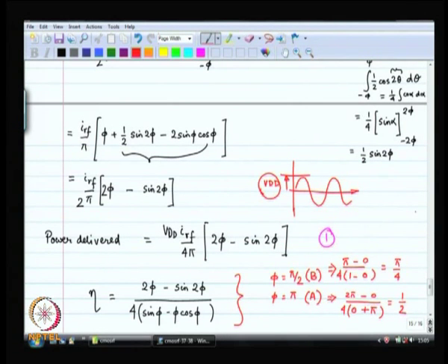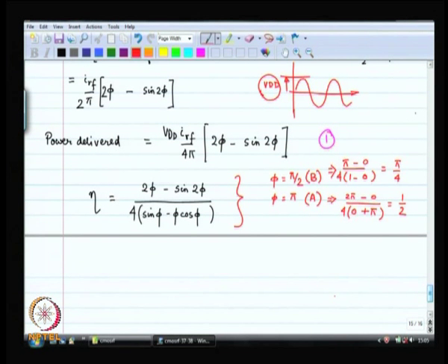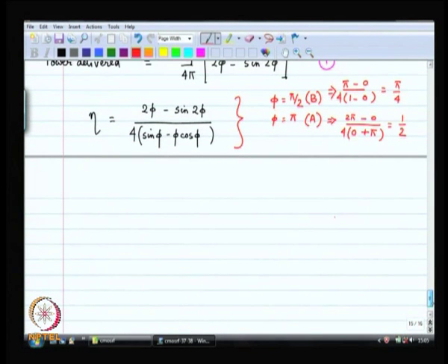All right, you need a little bit of room to allow for the transistor to remain in saturation. So, a little bit of room is needed over there. If you do not allow that room, then your device is going to cut off at a place where you do not want it to cut off, right. When the current is maximum, that is where the device is likely to cut off.